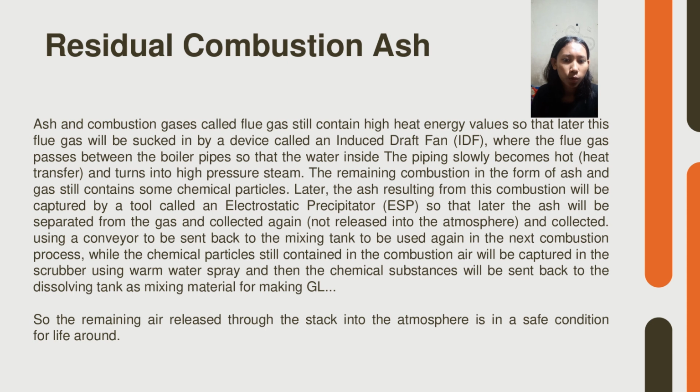The chemical particles still contained in the combustion air will be captured in the scrubber using warm water spray, and then the chemical substances will be sent back to the dissolving tank as mixing material for making GL. So the remaining air released through the stack into the atmosphere is in a safe condition for life around.